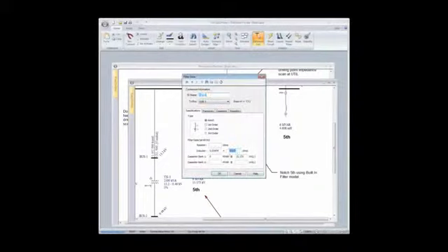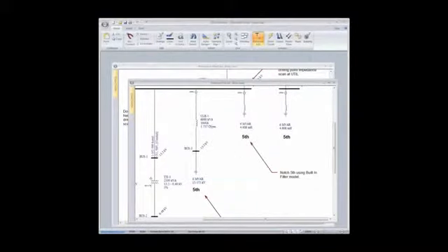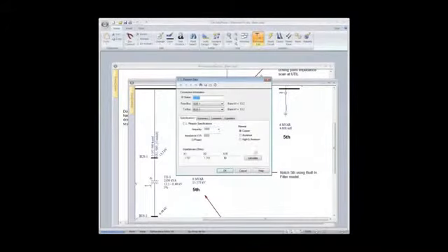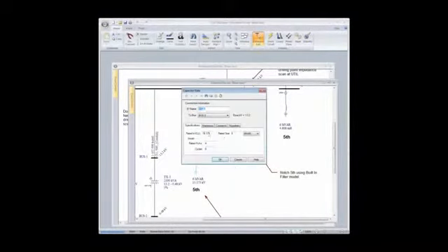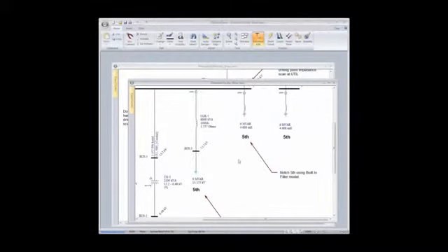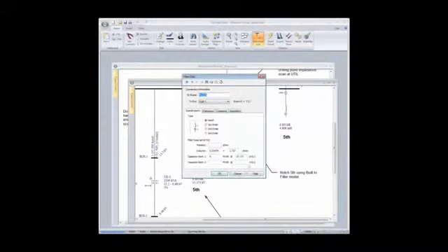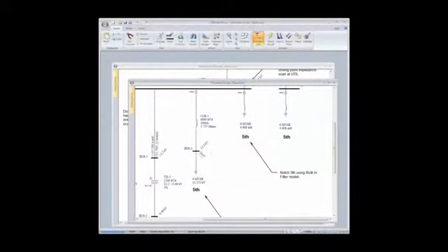So if you take a look here, it's 1.737 ohms with this resistance, which gives me an X over R of 50. And so I put in 1.737 and 50. Here we have the capacitor broken out as a 6 megavar bank, specified at 15.173 kV line to line. And this one is identically the same. So if we want to see the bus voltage here for any reason, we may need to break these components out when we're doing filter design.